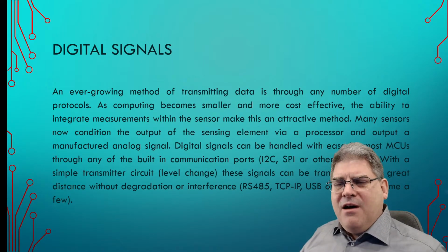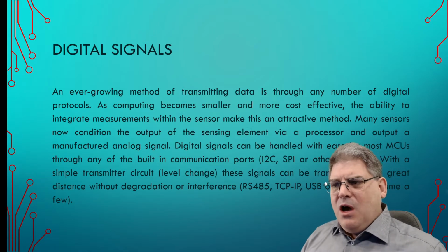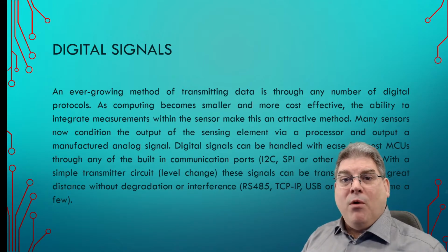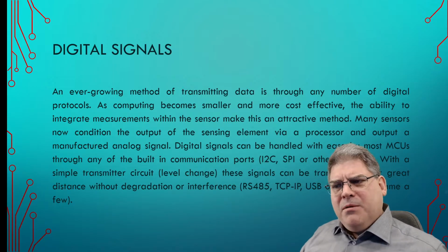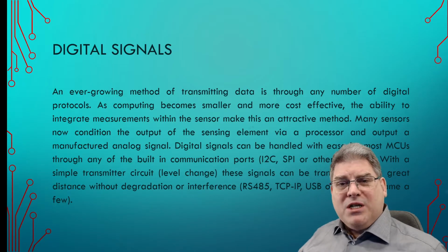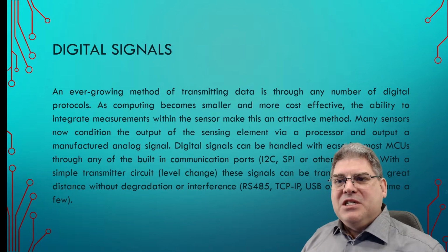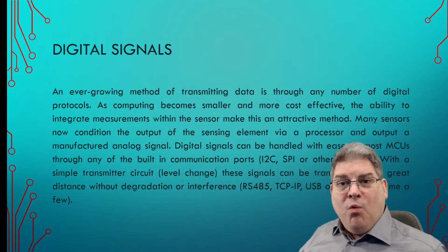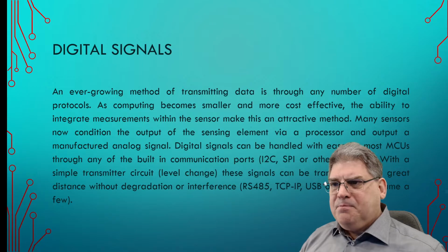And these have a wonderful advantage that they can communicate over very long distances, whereas the I2C or the SPI should really be kept on your circuit board for, again, noise issues. But because RS485, for example, has a buffer, it drives a much higher voltage and is not prone to the same noise issues. And so think about, when you're designing your system, how you want to communicate with your sensors, and how far away, what environment it's going to go through. All right.